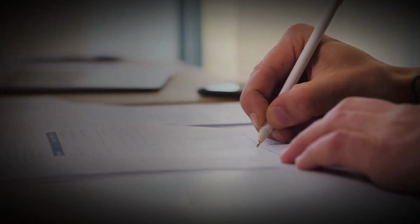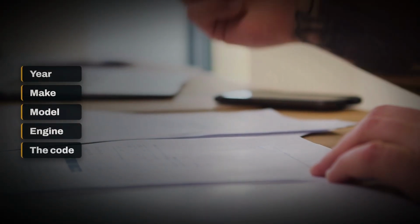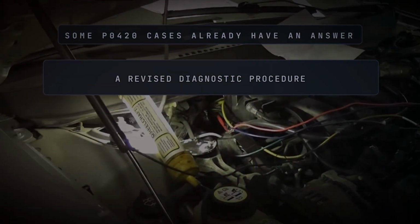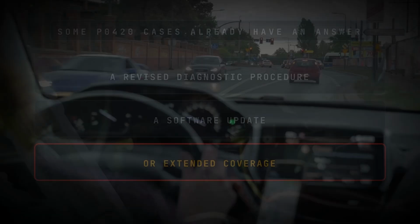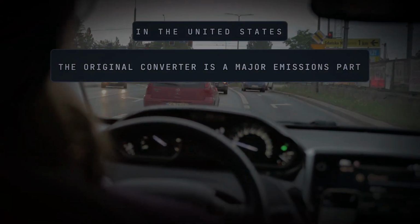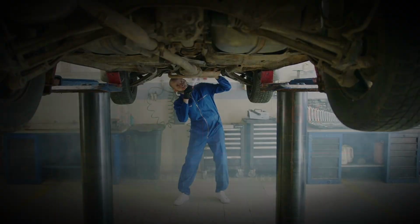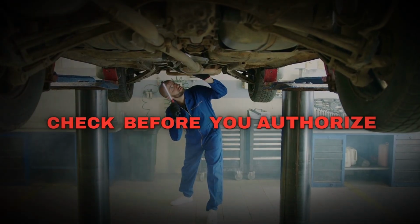Before paying for a repair, search the exact year, make, model, engine, and code for technical service bulletins or manufacturer campaigns. Some vehicle-specific P0420 problems have involved revised diagnostic procedures, software updates, or extended coverage. Also, check the vehicle's emissions warranty. In the United States, the original catalytic converter is generally included among the major emissions components covered for 8 years or 80,000 miles, whichever comes first. Coverage depends on the vehicle, the cause of failure, and the manufacturer's claim procedure. Check that before authorizing the repair.